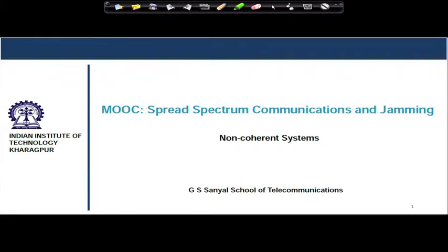Hello students, in this module we will now discuss non-coherent systems. Basically the target is to see, for non-coherent communications, how we despread the signal, and whether the matched filter architecture that we already discussed in the last module is equally applicable here, or whether we need to put in a separate synchronization block to realize the system implementation.